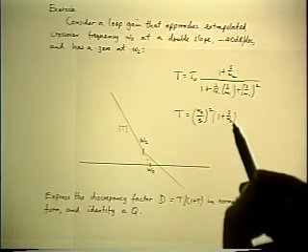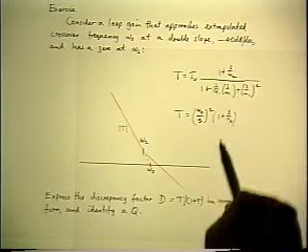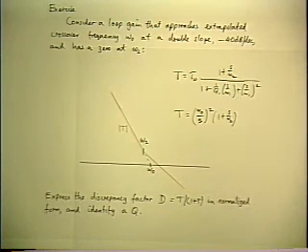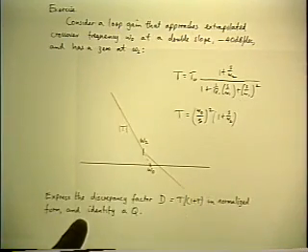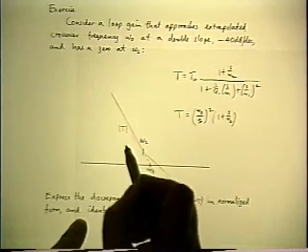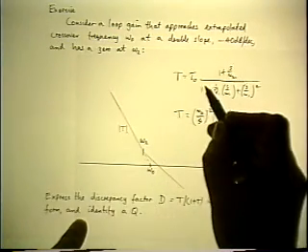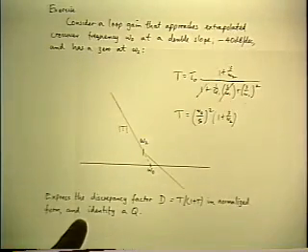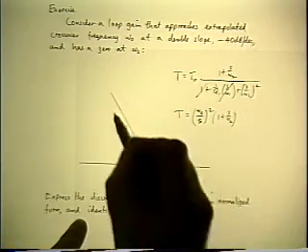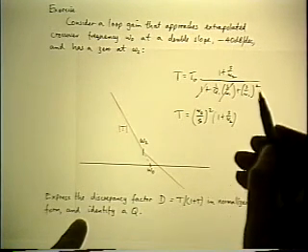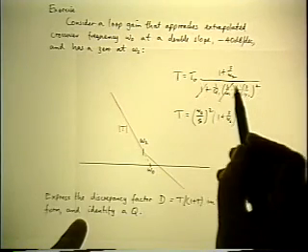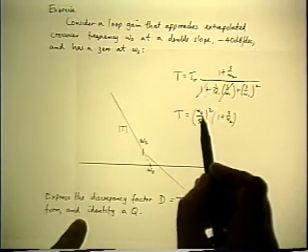Now, if you want to know what the relationship is between this version and the first one, then of course we could get the same result algebraically as well. Because what we've done is we've limited the first expression to frequencies that are well above the omega 1. By throwing away that part, we're only interested in the part relevant to higher frequencies, which is equivalent to throwing away this term and this one. Because the denominator will be dominated by the S squared term. And this is now the same result because the T0 times omega 1 squared is equal to omega 0 squared.